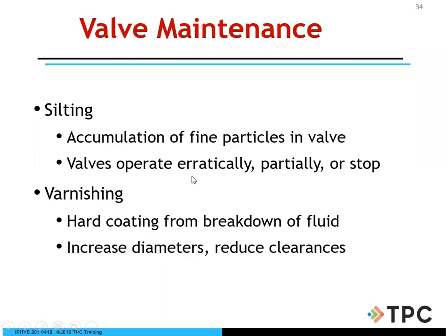Most of the time, we have solenoids on the solenoid caps. They energize it, but maybe they won't energize, and you have to go up there and manually actuate these directional control valves. That means something is stuck on the inside, because varnish begins to form on the inside of these directional control valves.